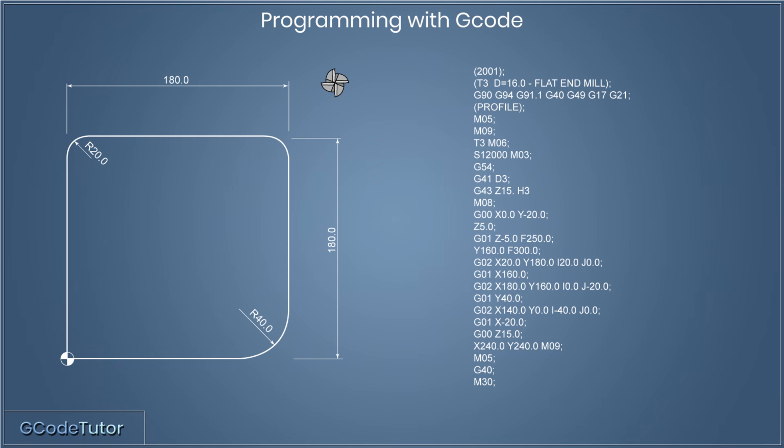Finally, we have the M code M30. Now M30 tells the machine we've finished the program and to rewind back to the start and stop and wait for our next instruction. An alternative to this would be M99. Now M99 would rewind the program back to the start and then continue running. This is not normally used on CNC routers, this is more of a CNC lathe thing. So M30 tells the program it's finished and rewinds back to the beginning of the program and stops.